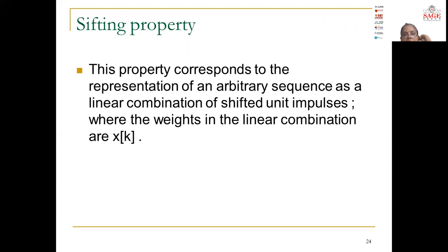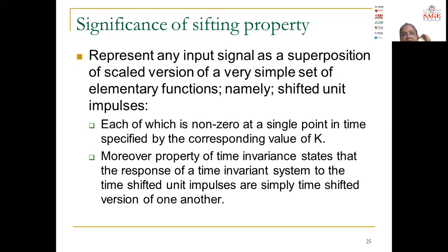Now this property corresponds to the representation of an arbitrary sequence as a linear combination of shifted unit impulses, where the weights in the linear combination are x[k]. What is the significance of this property? It is a scaled version of a very simple set of elementary functions, each of which is non-zero at a single point in time. Moreover, the property of time invariance states that the response of a time invariant system to time shifted unit impulses is simply a time shifted version of one another.